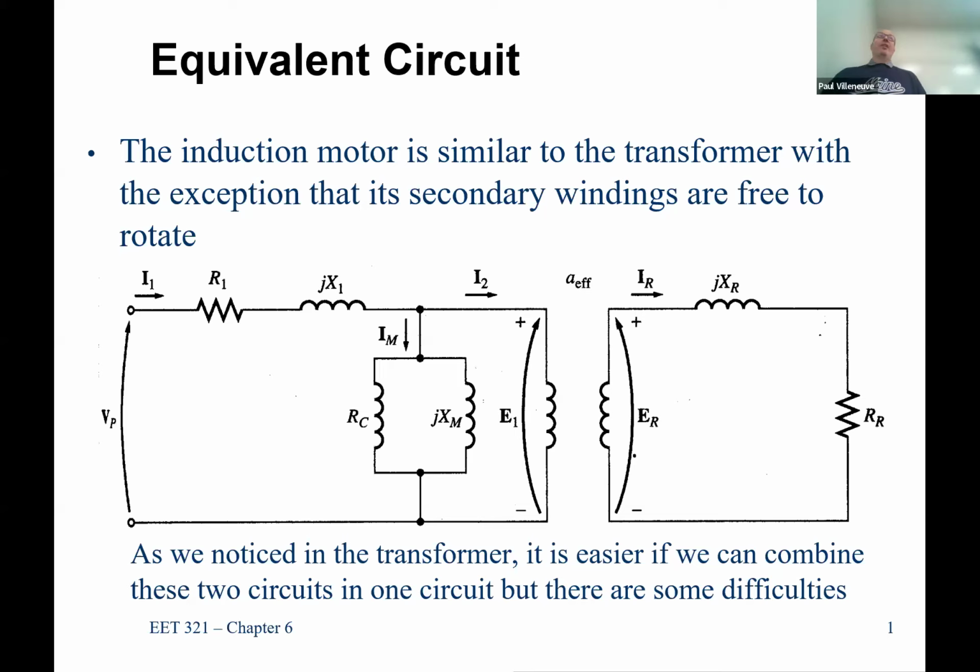Kind of sounds like a transformer, doesn't it? That's essentially what a transformer is. You've got an AC winding, and I said three-phase, but it's really single-phase. You have a primary and a secondary in a transformer, and you use magnetic energy to convert from the primary winding to the secondary winding to get that power flow. It's the same thing on an induction motor or an asynchronous motor. The difference is that on the transformer, the secondary winding is connected to the load, so we're delivering power to the load. Over here, there's a mechanical load. There is no electrical power being conveyed to something else. In fact, it's all mechanical power.